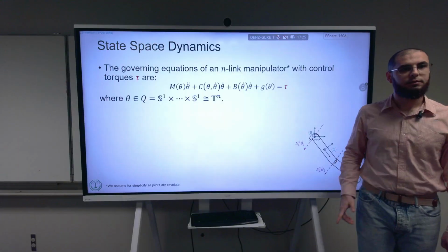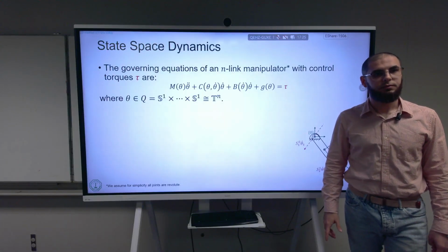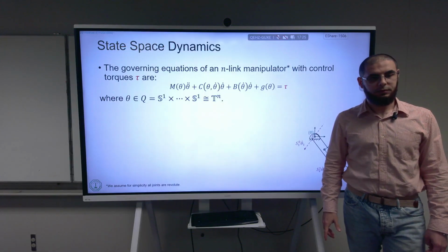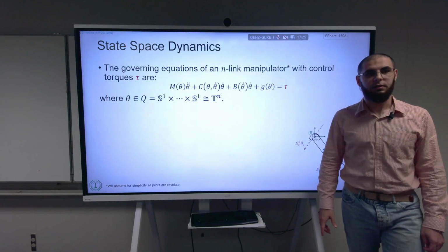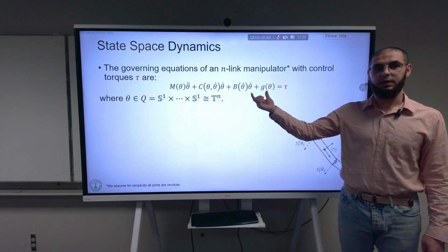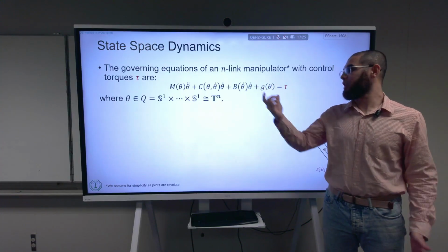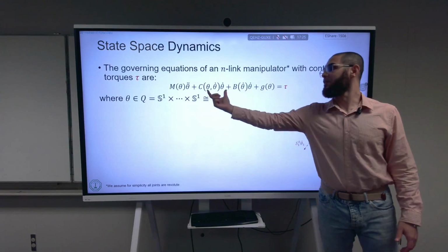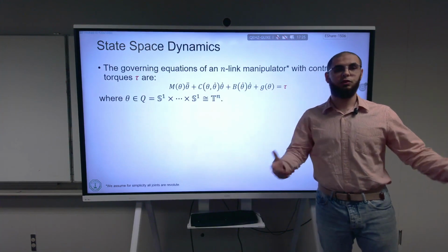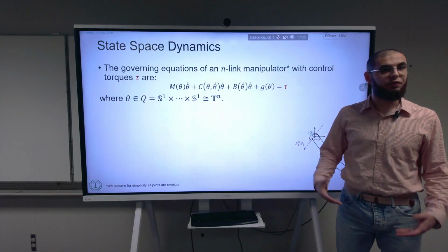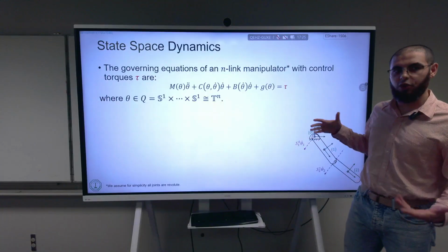Yes, Fahd. Okay, so if there's a term that's in a higher velocity, like for example, a function of v squared and v... Yeah. Is it in the C of theta? That's right, yeah. Coriolis? No, in the B of theta. So if it comes from friction, something that dissipates energy, then you put it in the B of theta. Because everything in the C here, they don't contribute to the energy balance. That's usually how it goes, okay? They're fictitious torques, actually. They're not real.